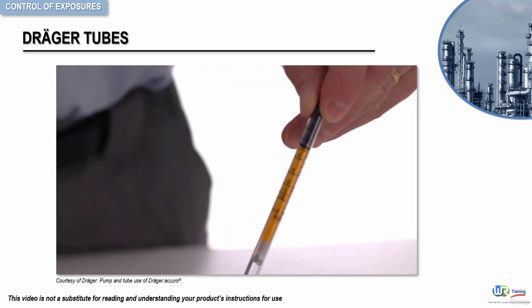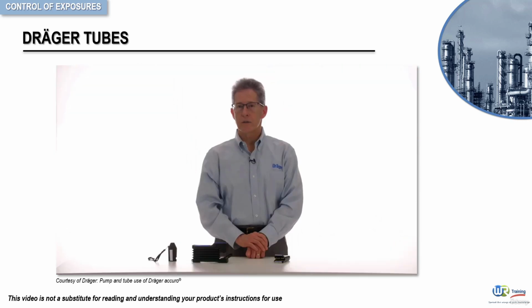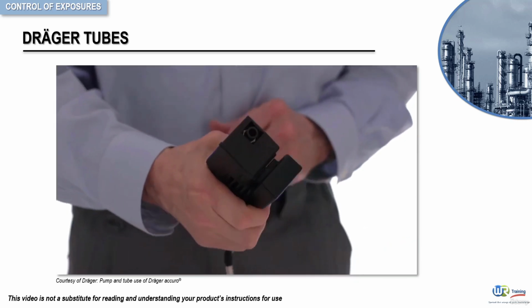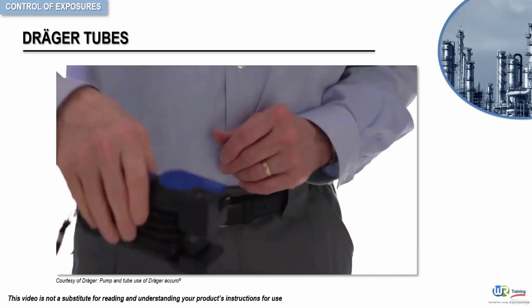Using an indelible marker, mark the end of the violet discoloration. The discoloration on the tube may change over time. Compress the pump 4 to 5 times after each test to flush the pump.